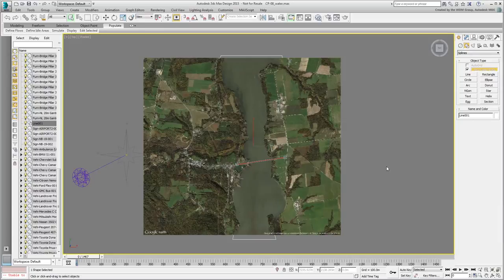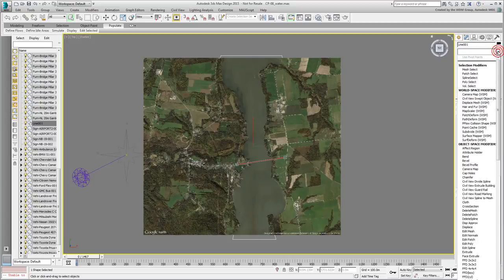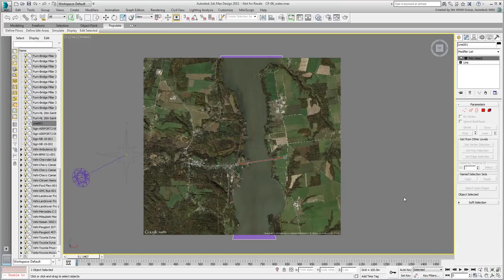To turn the spline into a surface you can render, add a Poly Select modifier to it. Note that you could also add an Edit Poly modifier, but since you can make adjustments at the spline level, a Poly Select modifier is enough. Minimize the top view again.